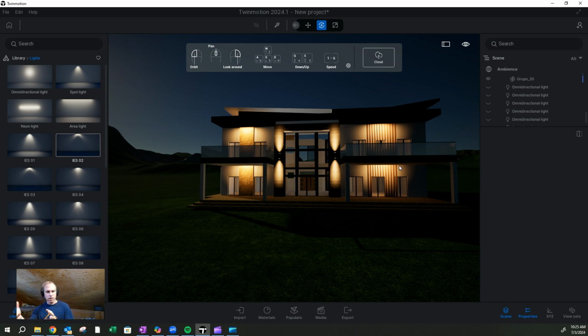And then instead of just going completely nuts, maybe it's just 6 fixtures on the outside. Like, hey, I want to highlight this, and then we're gonna still have the typical downlighting, so that way we can have it nice and bright when we want to entertain and guests are over. And that's going to be on a separate switch leg. That's where it's really helpful to have plans, to have it all mapped out, and wiring diagrams as well for the electrical contractors, so they're not wiring it on the same circuit or same zone. Or maybe if you're doing it yourself, I don't know. But just some thoughts there.